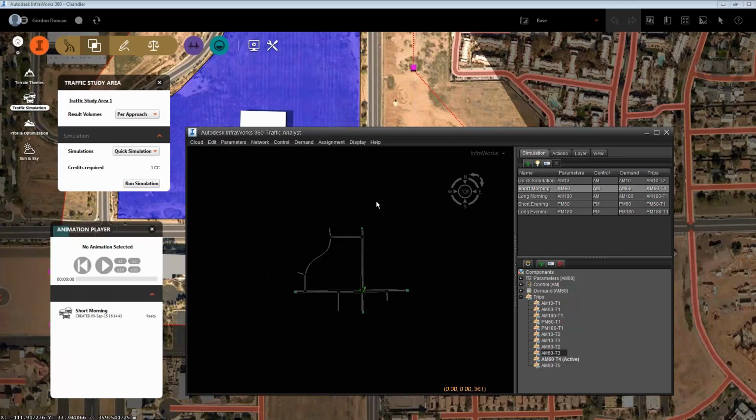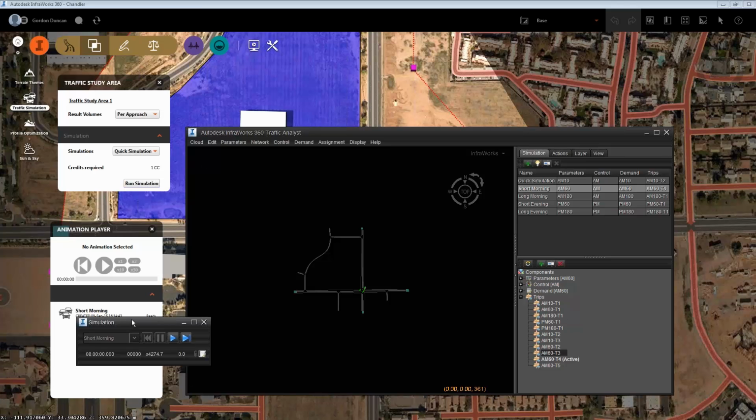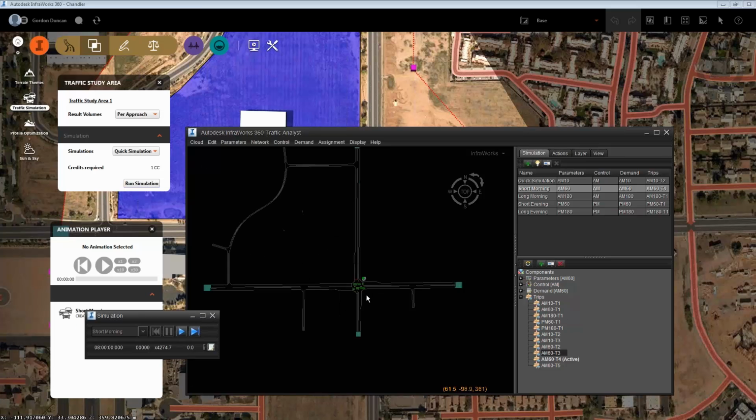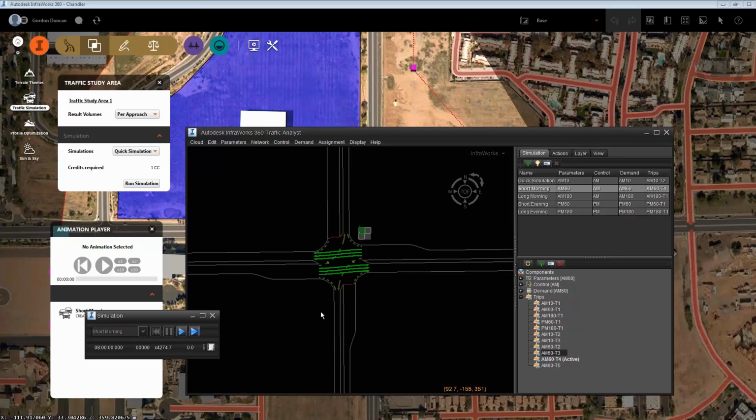Now, another thing that's new in the September release is that you can actually try that simulation locally now, just for a short period of time, just to check a few things that are going on. So you go to the Cloud menu in Simulation, and you use this button here to press play.